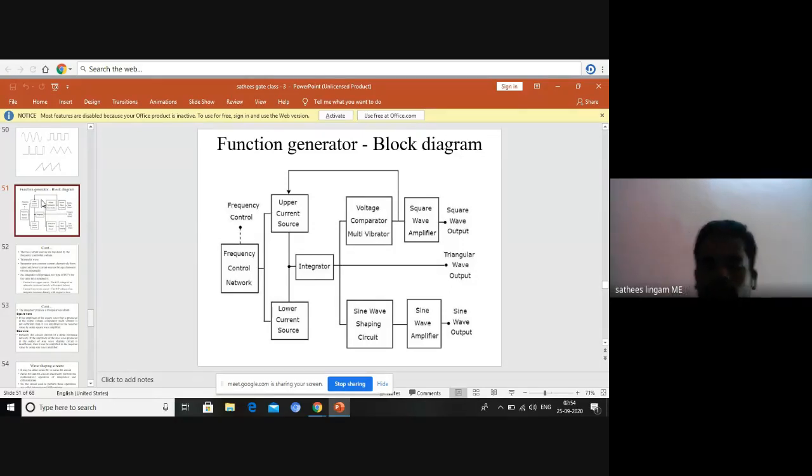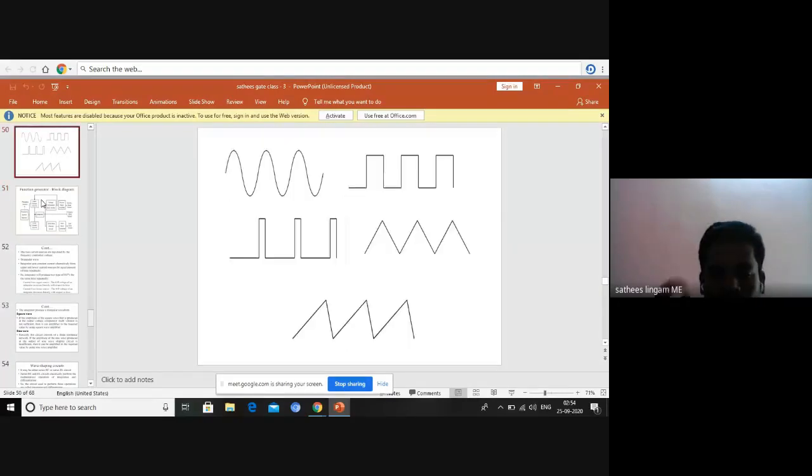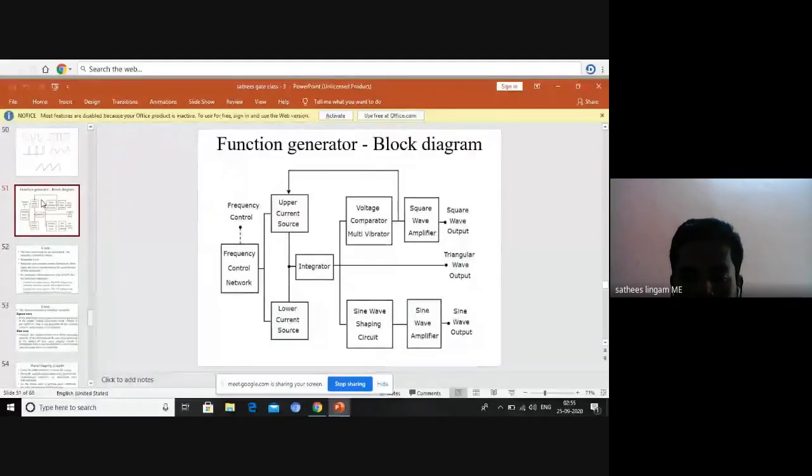If it is lesser than the threshold value, the output is fixed as 0. If it is greater, then take the average value. Suppose the triangle wave has an amplitude of 5 volt, the maximum height of the waveform. If you want to change it into a square wave, the threshold value will be 2.5 volt.